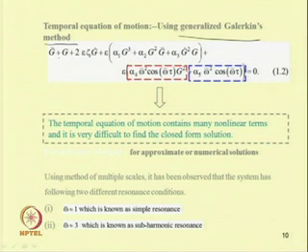form, that is G double dot plus G plus 2εζ G dot plus ε, where ε is a bookkeeping parameter which is very much less than 1, plus ε α₁ G cubed. This is the geometric nonlinear term and these two are the inertia nonlinear terms: α₂ G² G double dot plus α₃ G dot squared G, plus